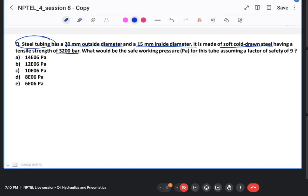Then your ability of the particular tube to sustain the fluid pressure. That is one of the most important considerations, because accidents in these hydraulic systems can cause potential hazards not only to the system but also to the workforce who is working around the machines. So these two are the main considerations. Then leakage is another thing. So this question pertains to the pressure rating for a particular steel tube.